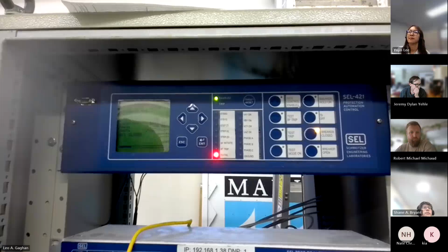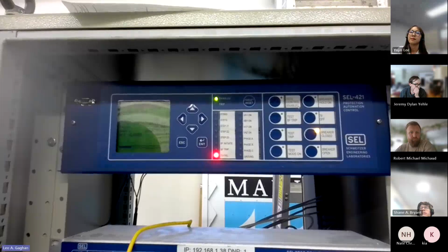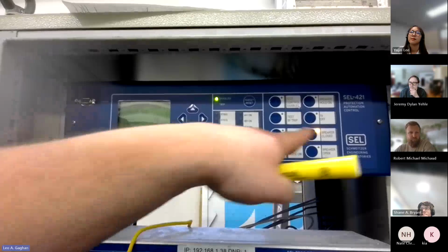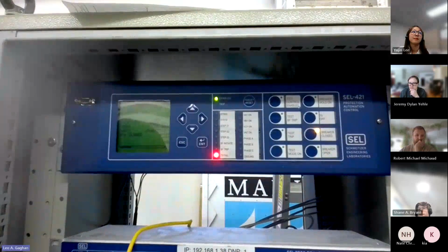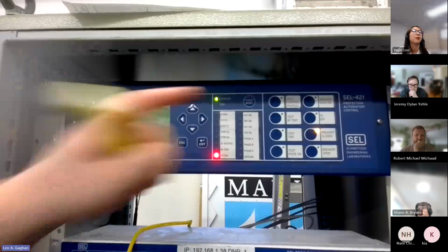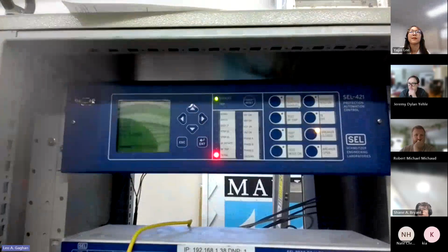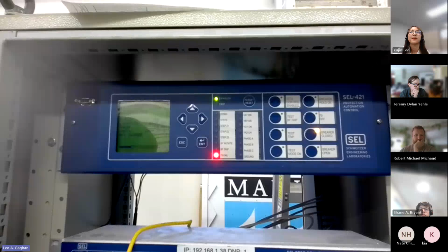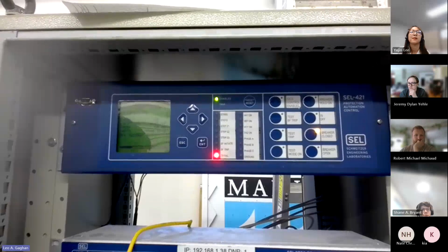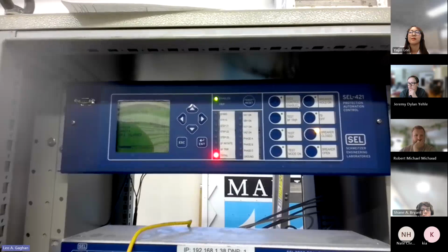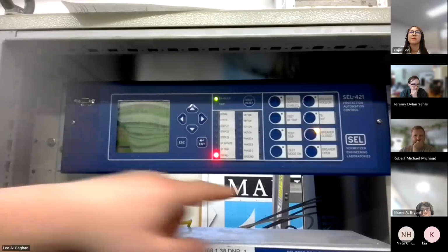Second, this breaker is closed. All right, we can see right there, the breaker's closed. So that part of the logic is good. We're not in hold, and the control switch is not enabled. We should be able to push the push button for a full second, have it come through here, hit the breaker 1 manual trip, and have that go through this internal logic, that output, which will actually open the breaker.